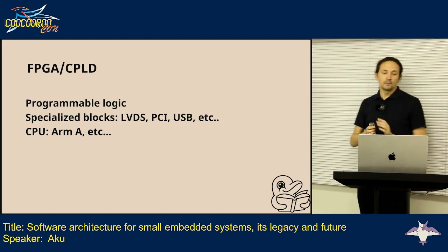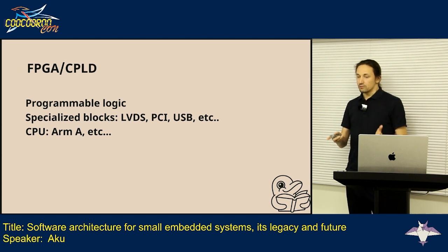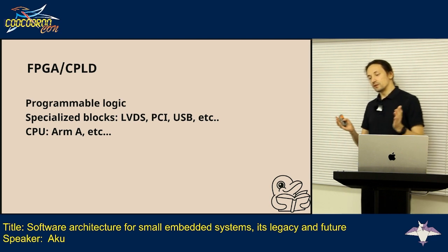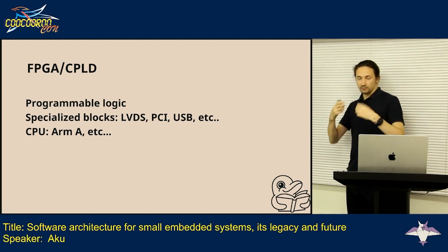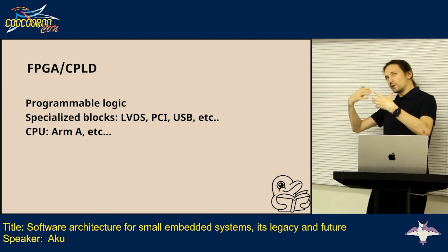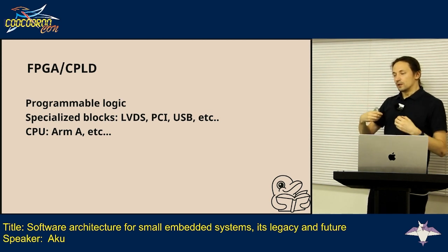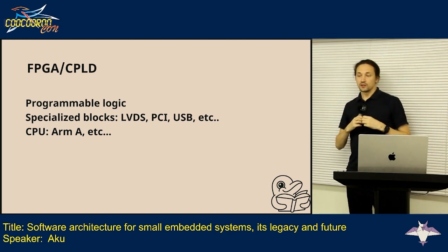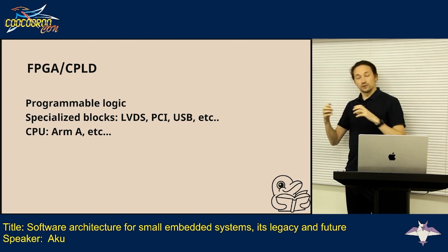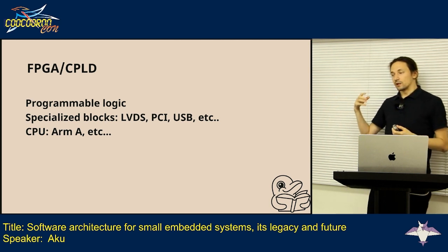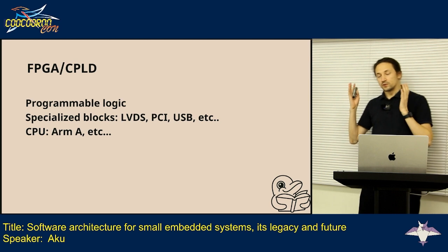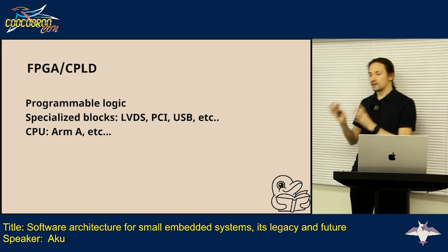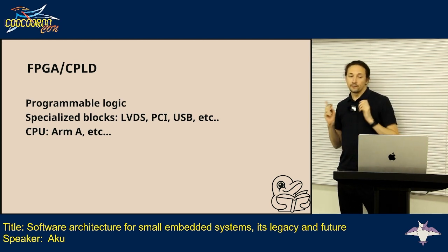but in hard real time. Usually, an FPGA or SPLD is just a bunch of logical elements and an interconnect fabric. So basically, the firmware for your FPGA or SPLD is just connecting those blocks together and building chains of logical elements. In some cases, we can add to those elements specialized blocks, like the ones for PCI or USB. In some cases, we can add radio, high-speed ADC, or DAC.